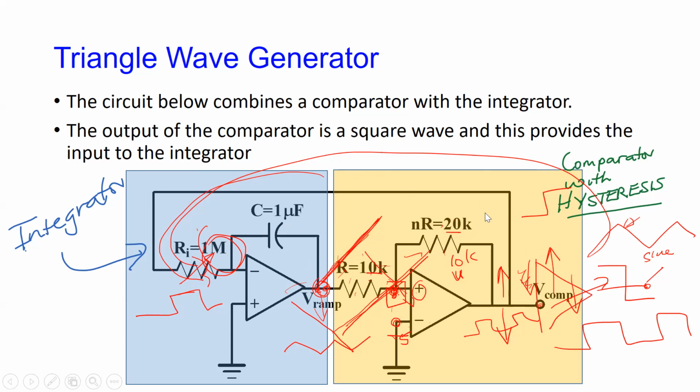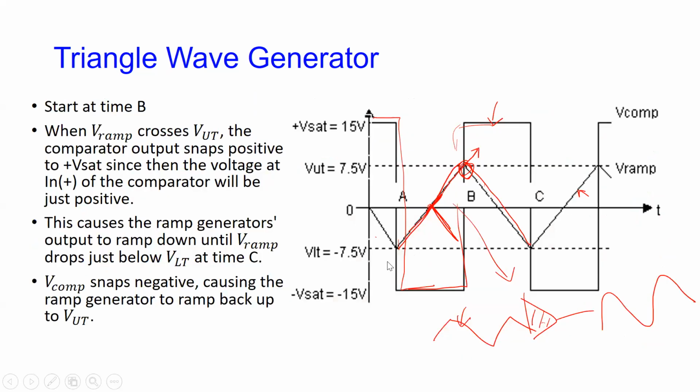That is the hysteresis delay, and you could add as much delay as is required to get the circuit working. Of course, that resistor also affects the amplitude that you get out of this. It's setting the upper and lower amplitude as well. All right.